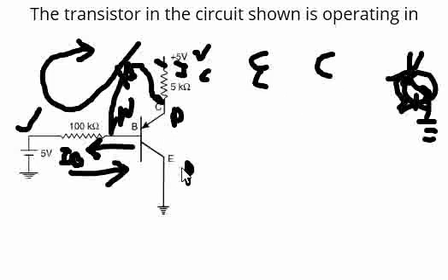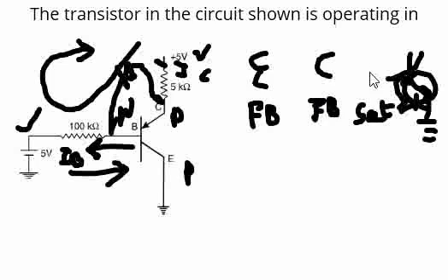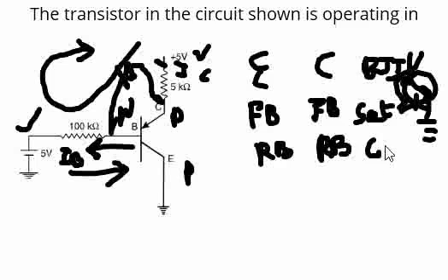Now, just for a generic understanding, if you have an emitter terminal and a collector terminal, if the emitter junction is forward biased and the collector junction is also forward biased, then in that case the BJT will be in saturation region. Now, if you have the emitter in reverse bias condition and collector also in reverse bias condition, then this will be in cutoff.